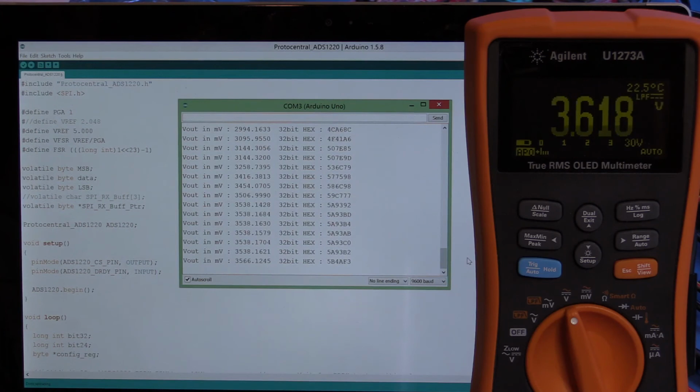So that's up to 4 volts, and it's tracking nicely, which is really good. So let's see if I can get this exactly to 4 volts. 3.999. Even a 10-turn pot when you're dealing with fractions of a percent is still quite hairy.